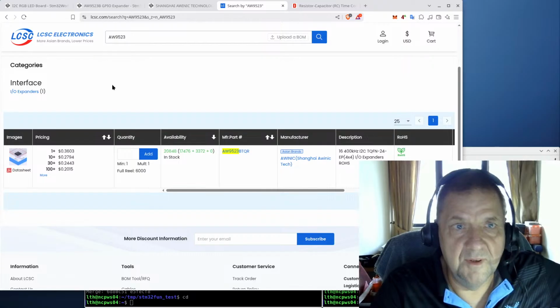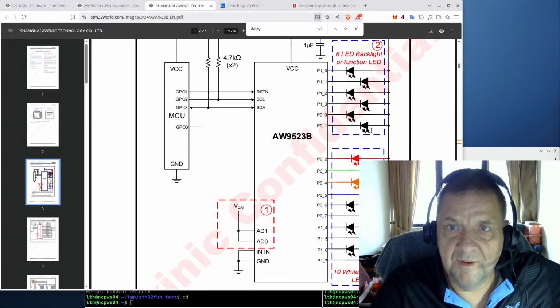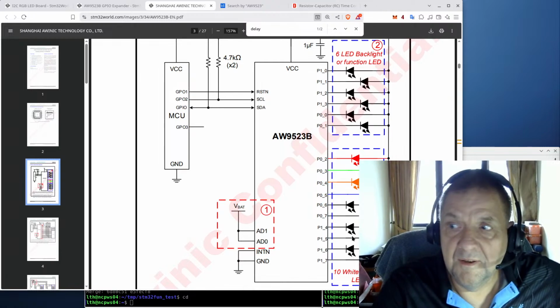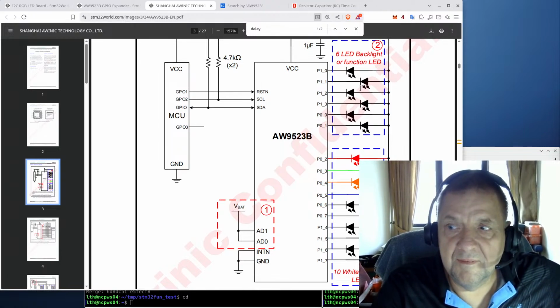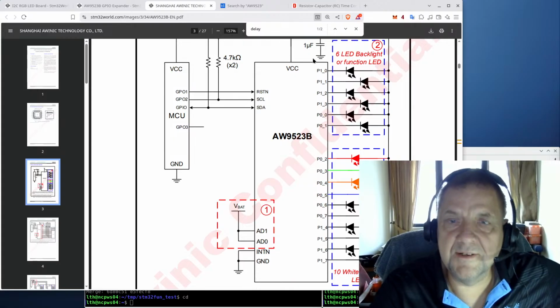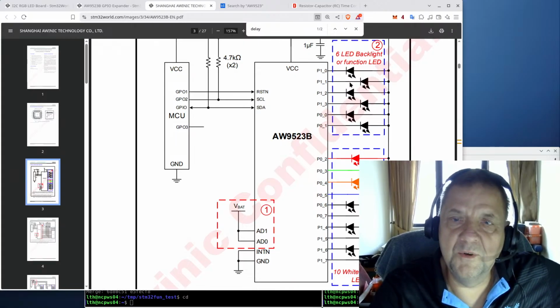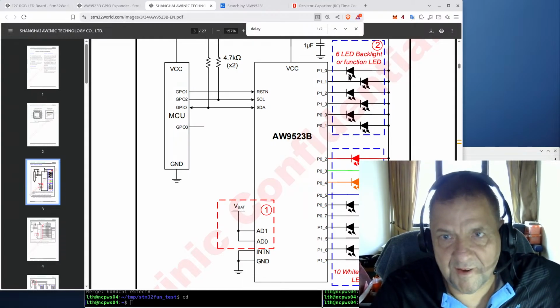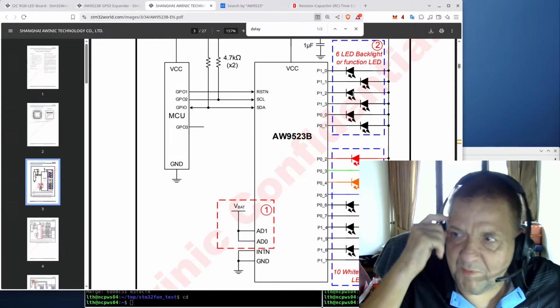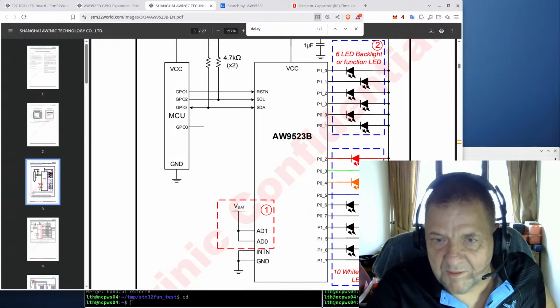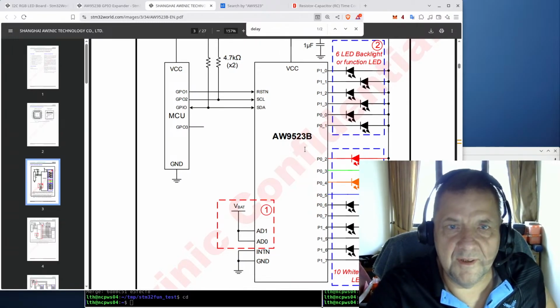So my thought was, rather than hooking up 16 individual LEDs, we could do that, but would that be more fun actually? Because you could use some nice patterns. But never mind. I'm going to hook up 3 RGB LEDs. No, 5 RGB LEDs. Why 5? Well, 5 times 3 pins on each RGB LED, that's 15, so I'll leave one port unused on this.